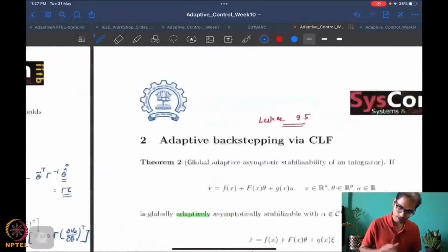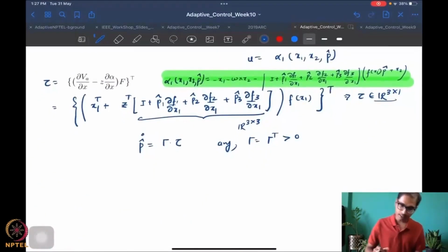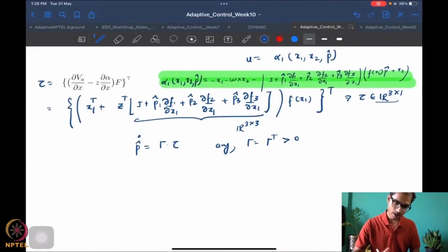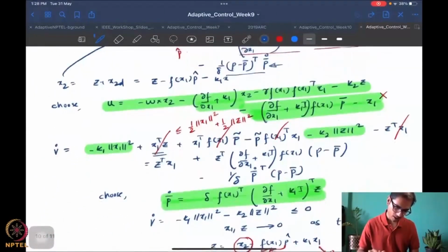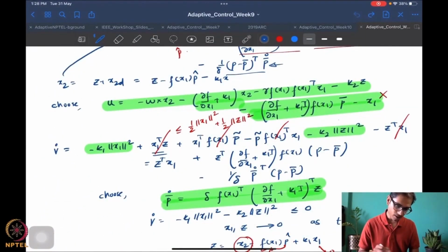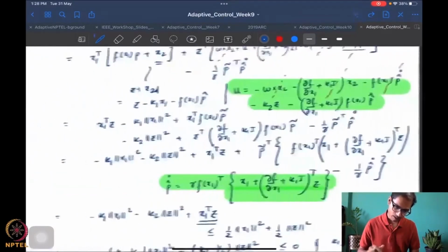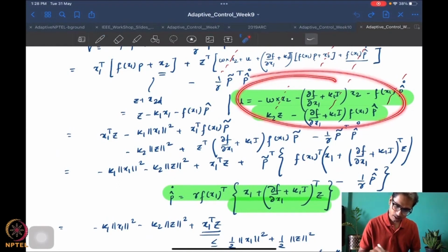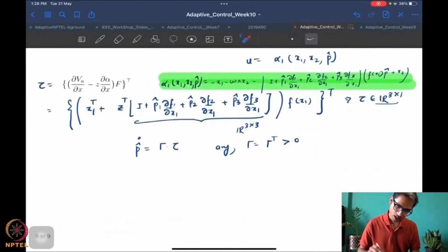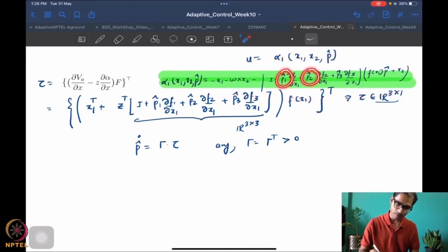The interesting thing is that if you look at the control law here and try to compare it with, say, the unmatched case control law, actually let's try to compare it with the extended matching case, where the control law is something like this. In fact, it looks rather simple, and our control law looks rather complicated. In fact, it has quadratic terms in p hat.